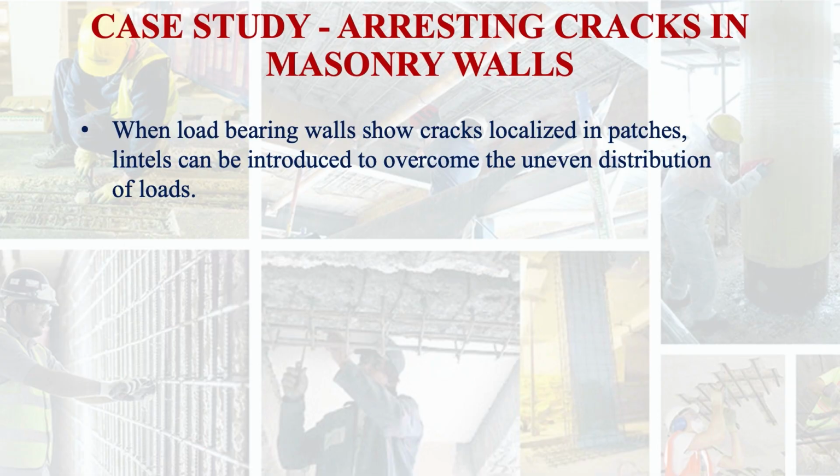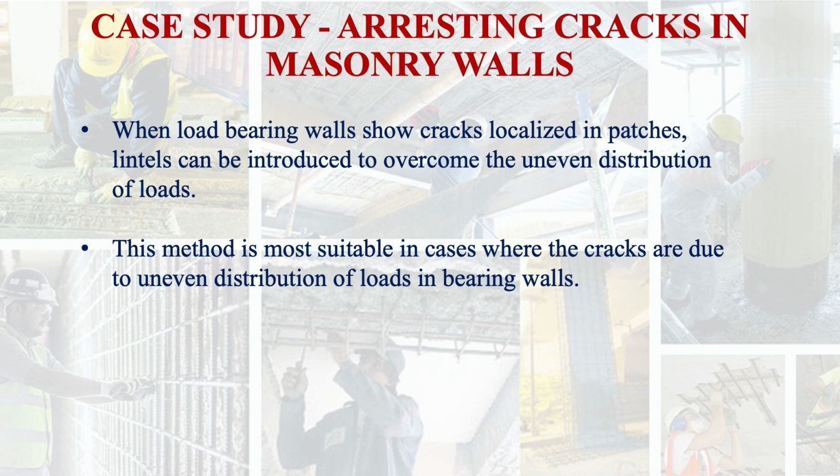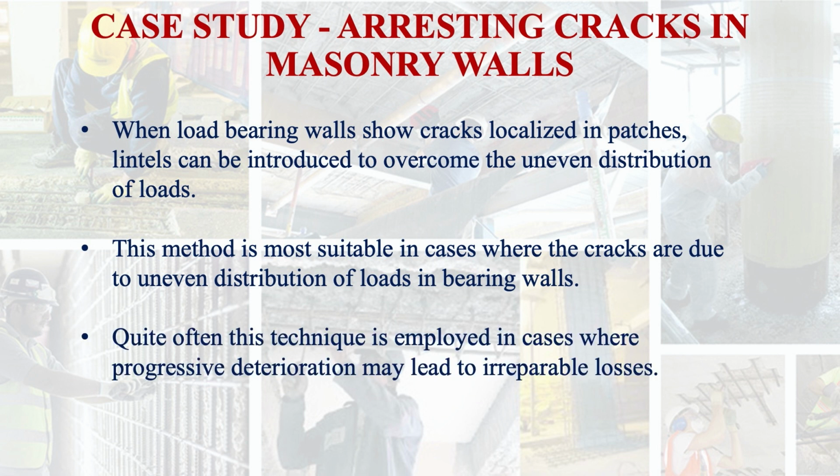When load bearing walls show cracks localized in patches, lintels can be introduced to overcome the uneven distribution of load. This method is most suitable in cases where the cracks are due to uneven distribution of loads in bearing walls. Quite often, this technique is employed in cases where progressive deterioration may lead to irreparable losses.